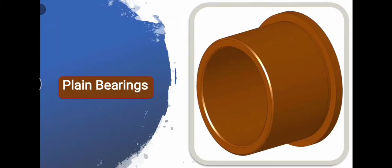Type number 3. Plain bearings. A plain bearing is the simplest type of bearing. It usually only consists of a bearing surface. There are no rolling elements in plain bearings. Plain bearings are used for rotational, sliding, reciprocating, or oscillatory motion. The bearing remains fixed while the journal slides on the bearing's inner surface.